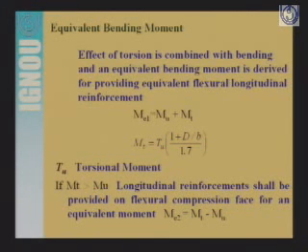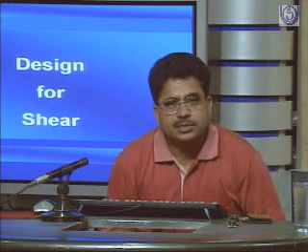Otherwise, if Mt is not greater than Mu, this longitudinal reinforcement will not be provided on the flexural compression face. But if Mt is greater than Mu, we have to provide this reinforcement for a value of Mt minus Mu.